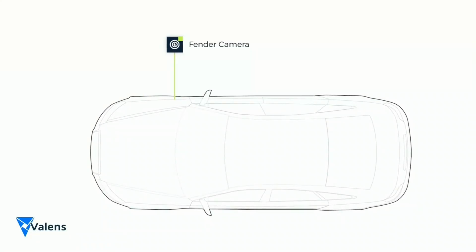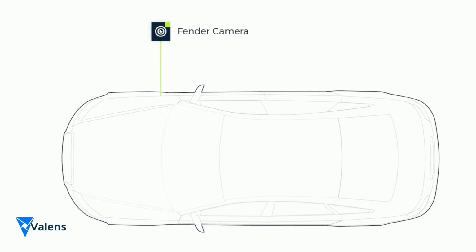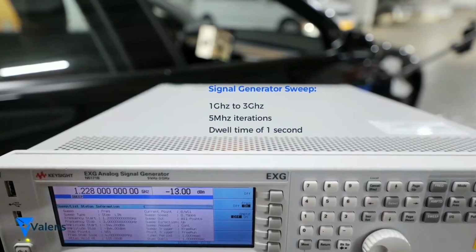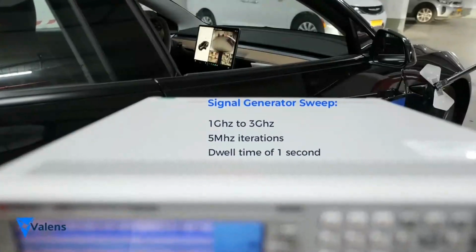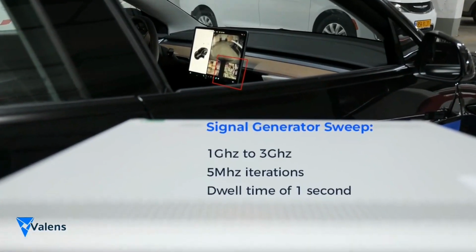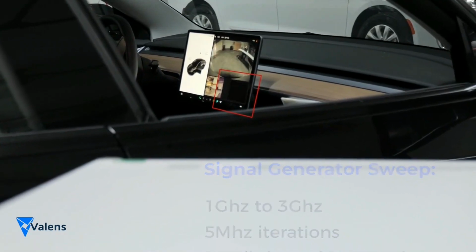In this video, we will demonstrate an example of this vulnerability using a signal generator to inject electromagnetic noise into an ADAS system at levels far below the industry standard. As you can see, with the introduction of the noise, the video from the far right fender camera flickers and ultimately fails.